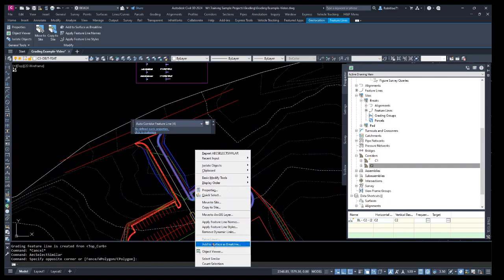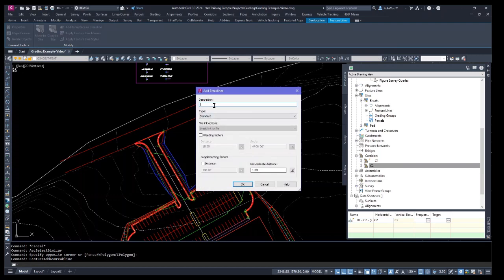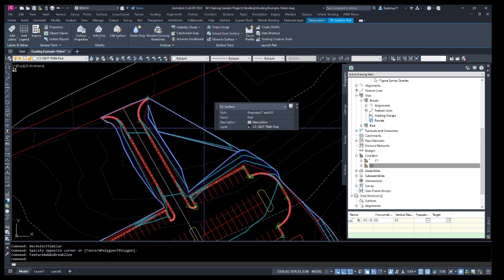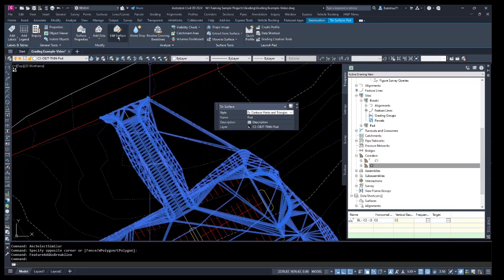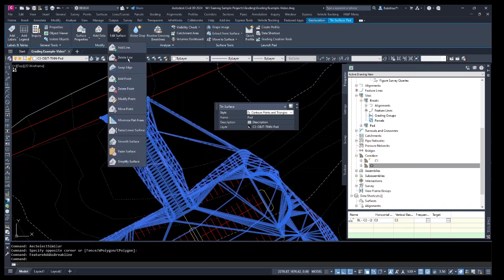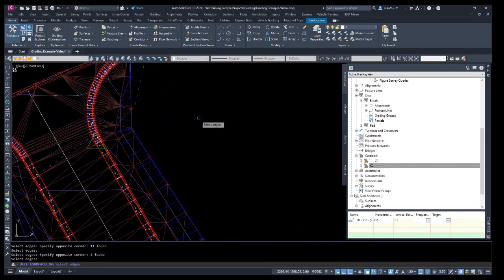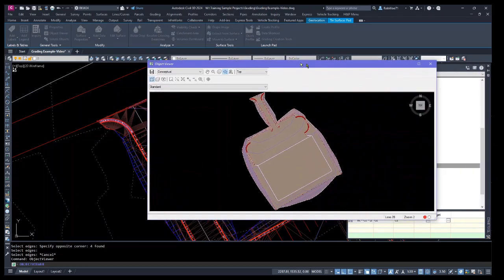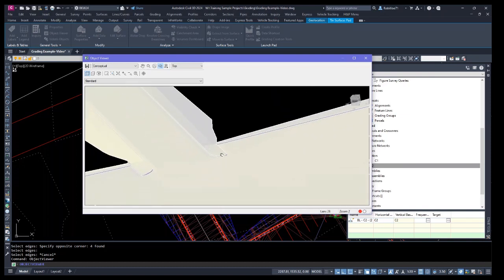Now if you right click, you can just add to surfaces break line, pad, and we'll call these again C2 and hit OK. Now from time to time it will regrade some of this, and that's easy enough to fix. Just change it to contours, points, and triangles, and then you can just delete these exterior lines that you don't want. Hit OK, and then let's look at it in the object viewer. There you go. Now you've added your second curb.